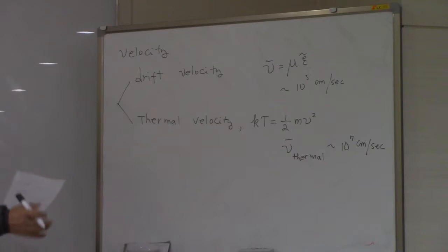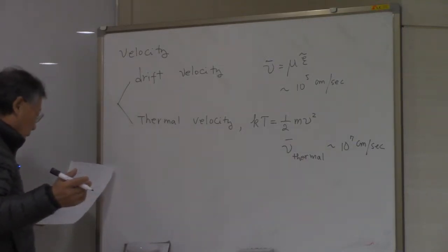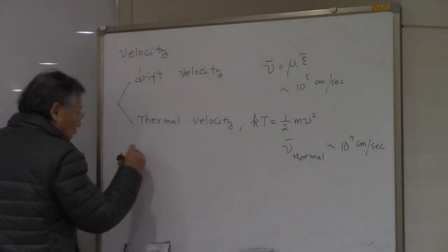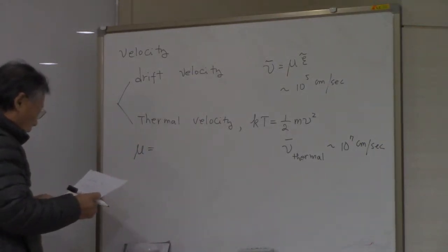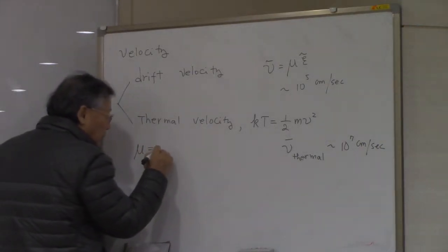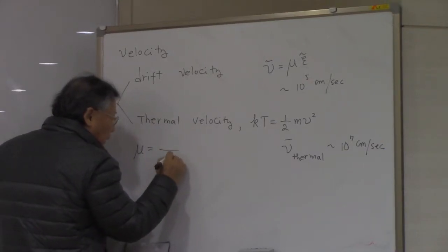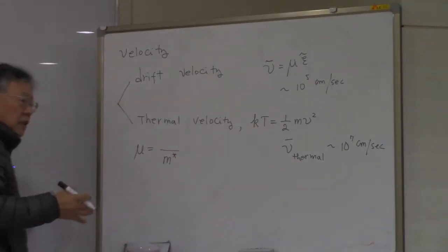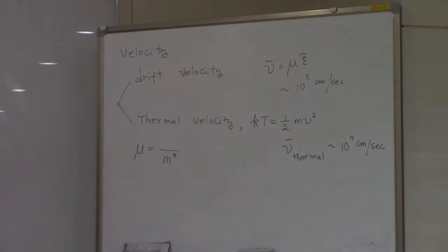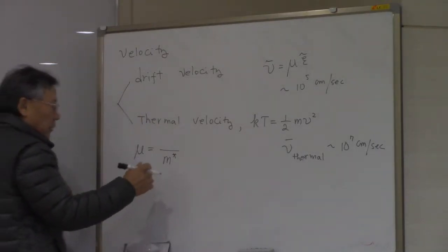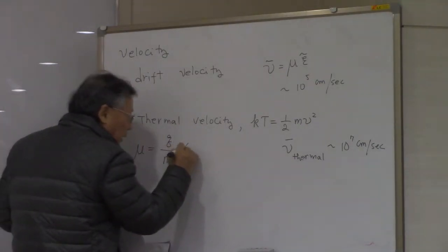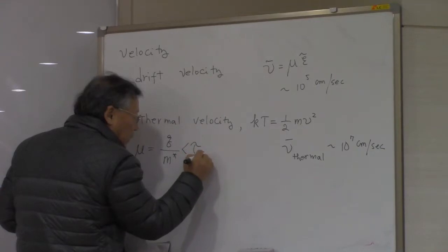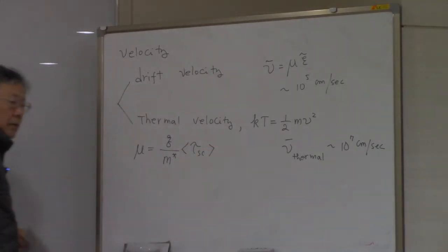And the mobility, we have deduced the equation related to the mobility, and intuitively what we have is that the mobility of any substance is inversely proportional to the mass of the material, and proportional to the charge it has and the scattering relaxation time.